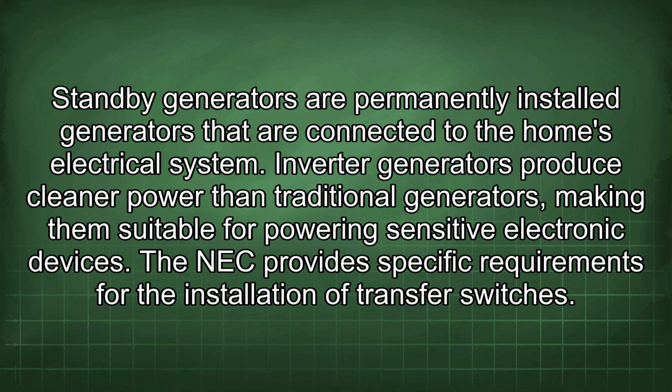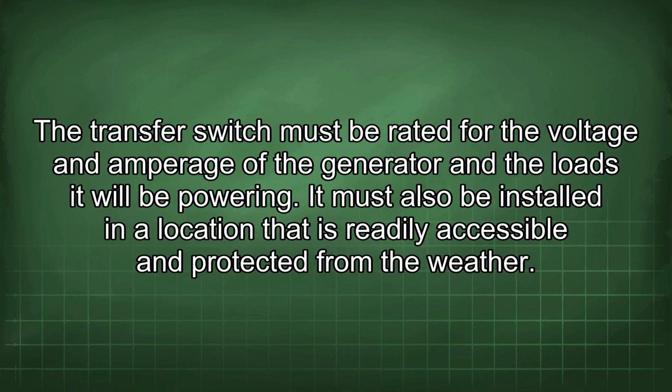The NEC provides specific requirements for the installation of transfer switches. The transfer switch must be rated for the voltage and amperage of the generator and the loads it will be powering. It must also be installed in a location that is readily accessible and protected from the weather.